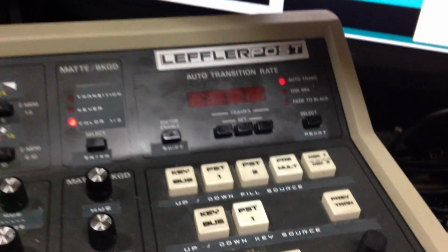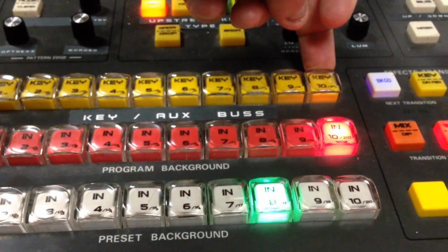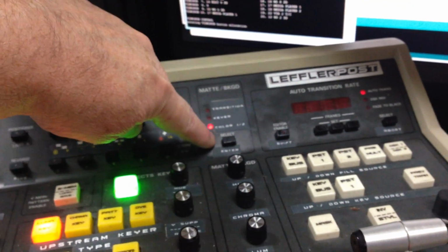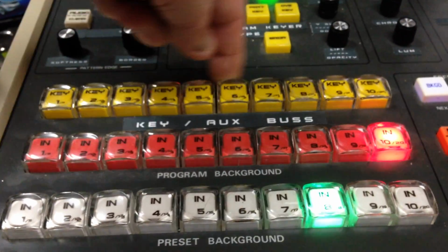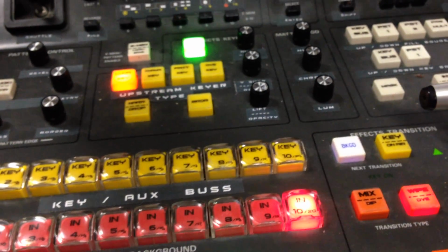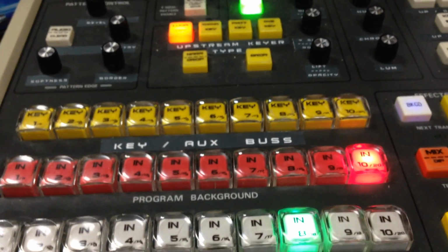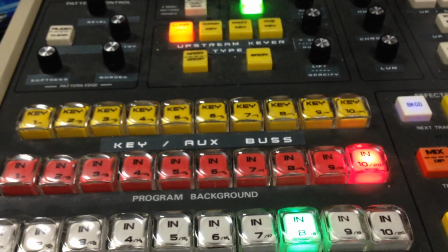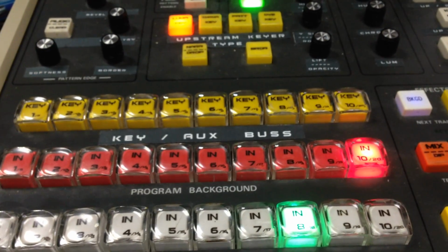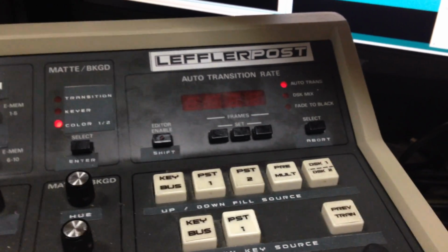The display's gone off, and it's now waiting for me to select any one of the 10 key bus buttons for inputs 1 to 10. Holding my finger on the shift button, I'll then be able to program 11 to 20, the allocations for the crosspoints. These crosspoints are for all destinations, so this particular set of programming doesn't bother with the destination, because no matter what destination you're on, these sources will be what is selected to that destination. The reason the panel's gone blank is because it's waiting for us to select which particular button we want to program.